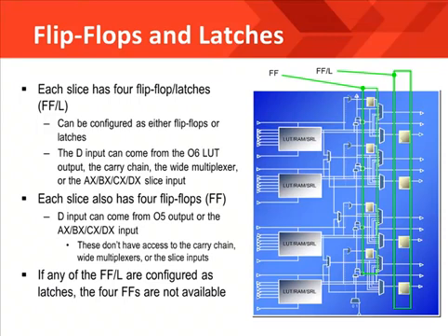These limitations are not as much of a big deal. In the end, if you're building lots of lower input functions that share inputs, as is required to have the 6-input LUT broken into 2 5-input LUTs, you should end up with the flip-flops being used quite a bit, and this will aid your pipelining and improve the speed of your design.